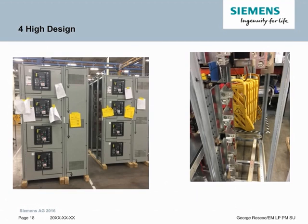These slides show an example of the 4-high design in actual production. The breakers are on the left and the pull section to the right. In addition, the right picture shows the lugs and how they're located. They are located facing the user at the front of the gear, and this section was optimized to have some lugs go at the bottom and top. And one other tip of the trade is the best way to optimize is have slightly more lugs going out the direction opposite of the through bus, because the through bus will restrict your conduit space on whatever side it is on.